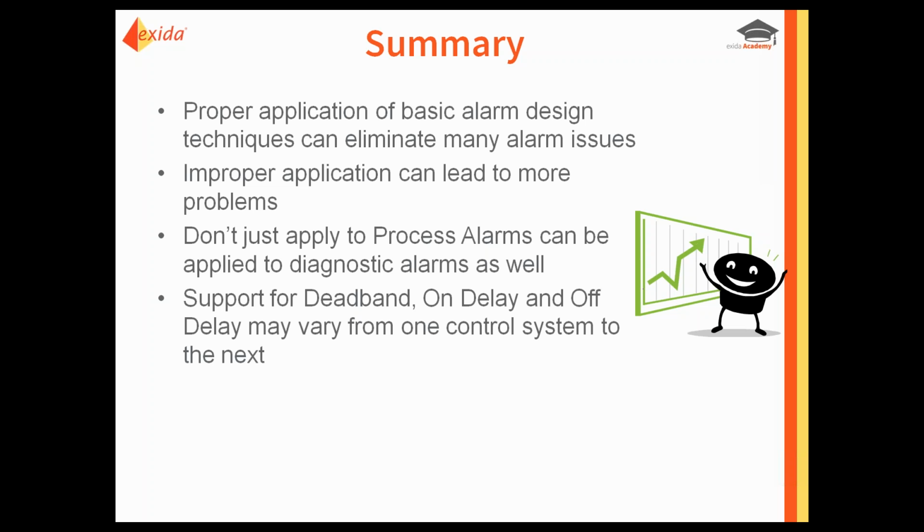And implementing on delays and off delays for those might be the key to making the operator's life a lot more bearable. And as I mentioned also, support for on delay and off delay and deadband may actually vary depending upon the type of control system. But going forward, it's actually a requirement in the international version of the alarm management standard that control systems provide that capability going forward.